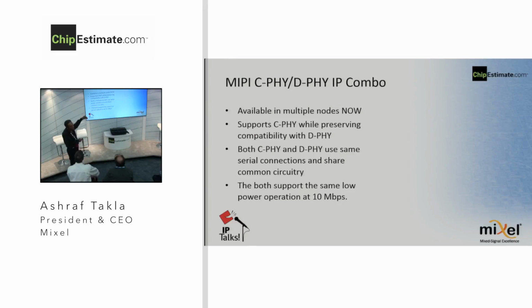They do share the low power operation. So the idea behind the combo is you can share the low power operation. You can also use, which of course is the low speed operation. Then you can also share a lot of, you're sharing the same pins, you're sharing the same traces on the board. We are sharing a lot of the common circuitry on the PHY.